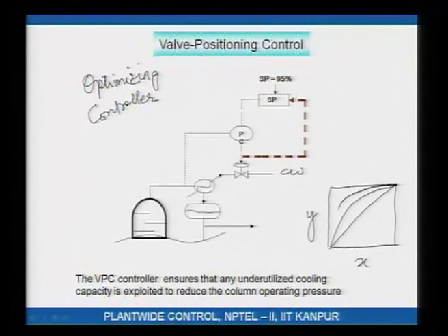If you keep decreasing the pressure, what you would see is this phase envelope moves away from the 45-degree line. So, in other words, if the pressure is increased, the XY envelope moves towards the 45-degree line. What that essentially means is, as the operating pressure of the column is increased, the separation gets more and more difficult. What is that supposed to imply?